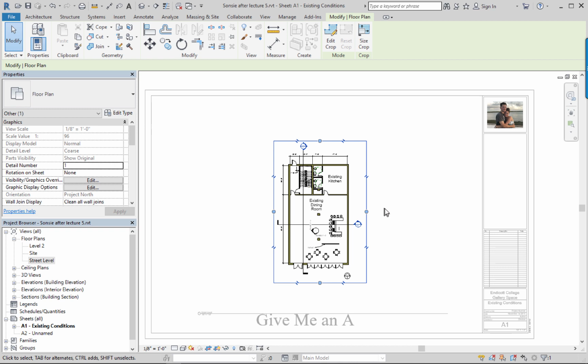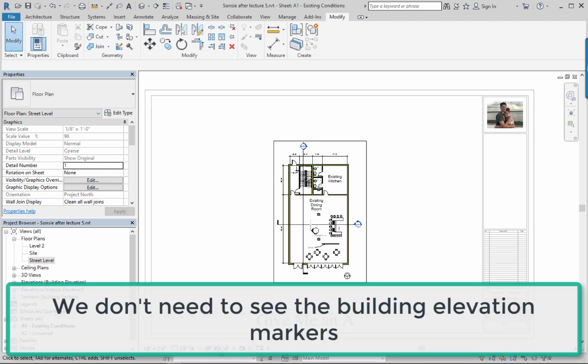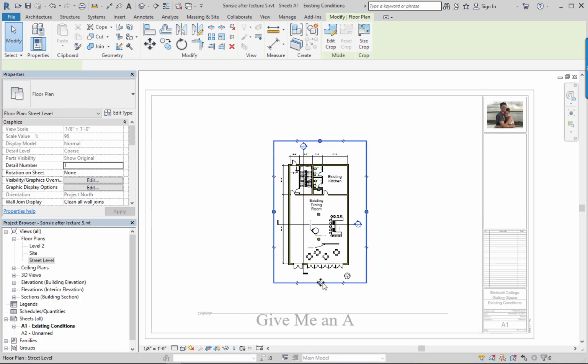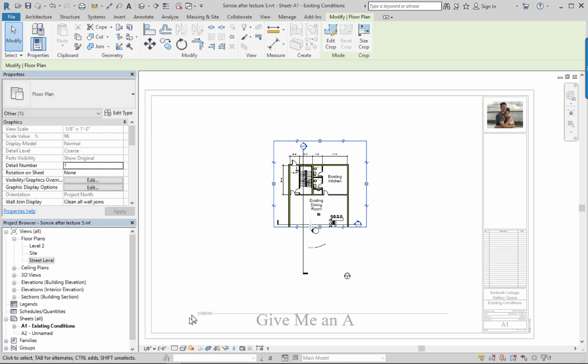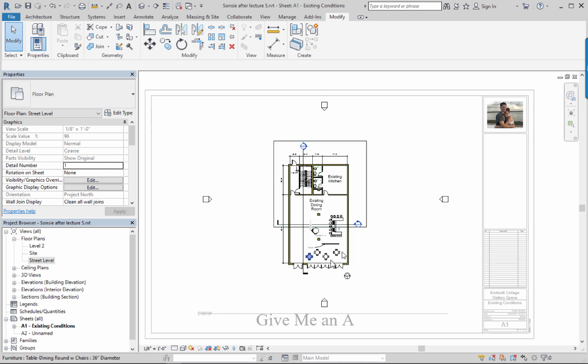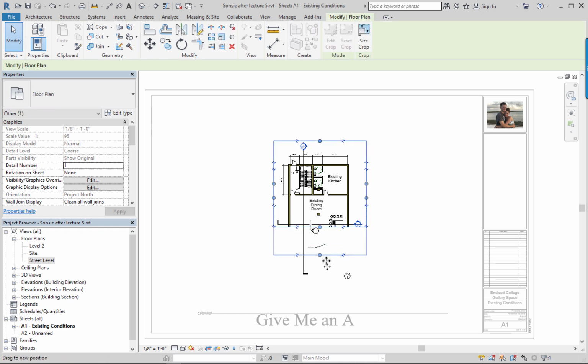Anyway, and that is how you can change the size of this drawing. You can also make the crop region hidden by just clicking this button. I'll show you what happens when I crop away part of the drawing. I can hide the crop region, and it just looks like the drawing disappears. If I turn off the cropping feature altogether, then it won't cut away the plan. Okay, so be aware there's a difference between turning on and off the crop region and just hiding it.